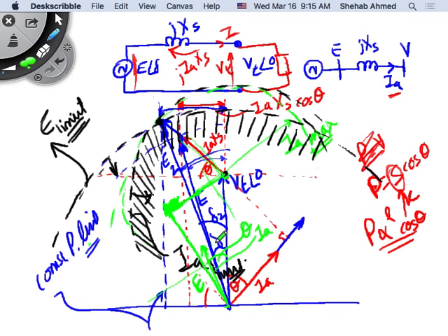I didn't increase delta too much, right? But what's happening now is I'm increasing delta too much. I'm not even increasing the real power, right? I'm actually supplying the same real power. I increased delta too much, close to my transient stability limits, which is somewhere the generator doesn't like to operate, right? So the generator, and what's happening inside the generator?